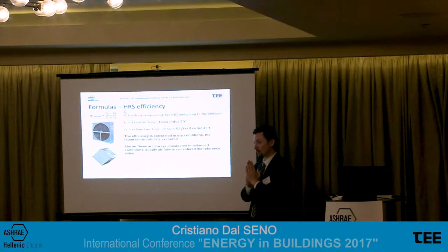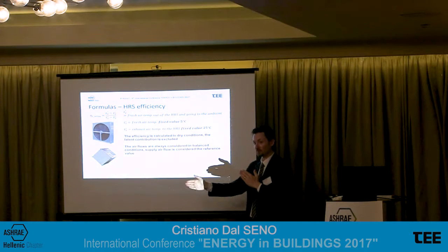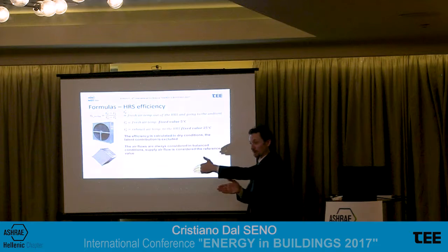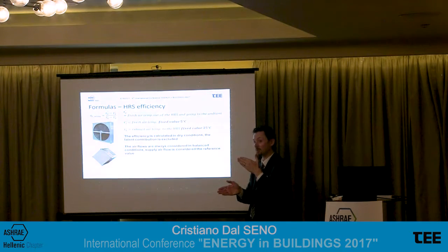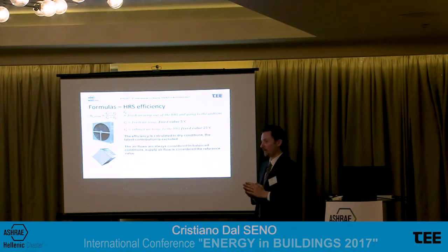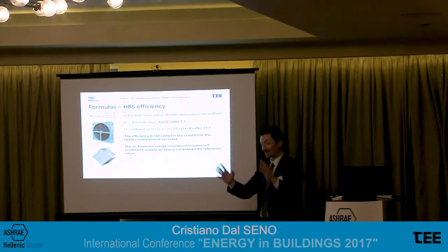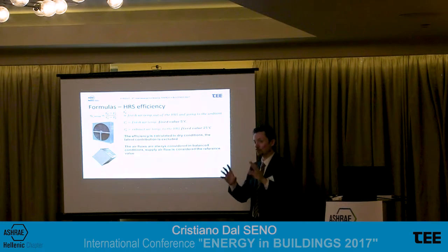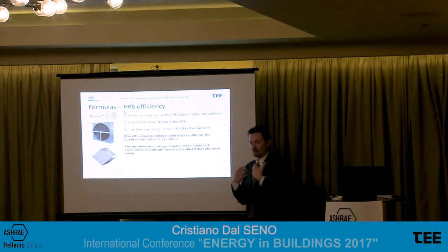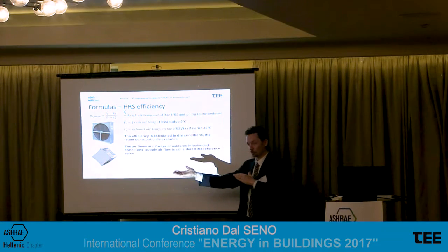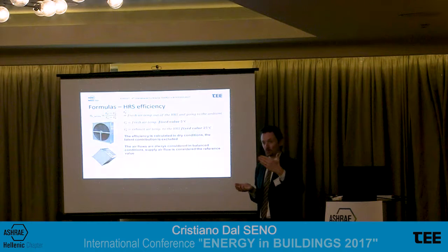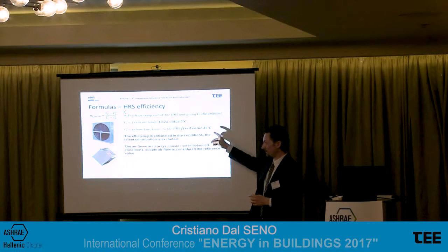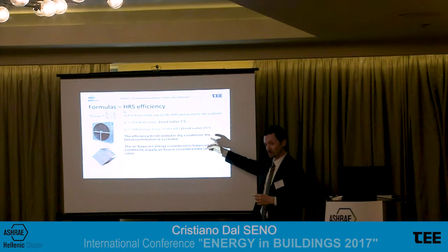So if on the supply you have 10,000 cubic meters, the calculation for the eco design will be with 10,000 cubic meters also on the exhaust. This doesn't mean that consultants are forced to do the calculation of their projects in this way. You can tell me, I want 10,000 on supply and 8,000 on the exhaust. But before giving the specification of the air handling unit, I will calculate the plate heat exchanger with these conditions.